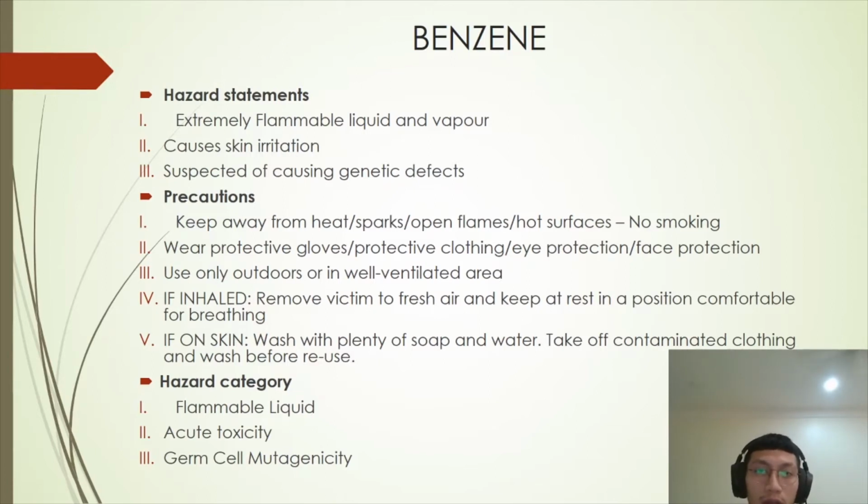Okay, the precaution of benzene is you have to keep away from heat, sparks, open flame, and hot surface. Besides that, you have to wear protective gloves, protective clothing, eye protection, face protection. After that, you have to only use outdoors or in well ventilated area. Besides that, you have to take precautionary measure against static discharge, and you have to wash thoroughly after handling. Wash your hands thoroughly after handling.